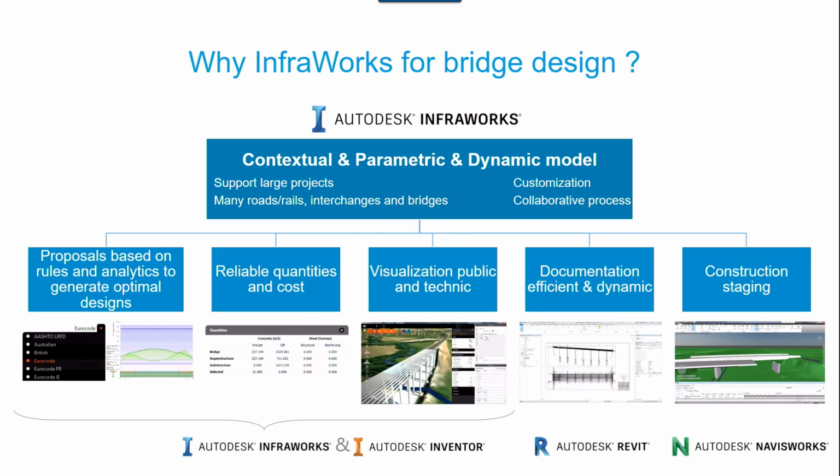You don't create the model floating in space like you can do in Revit, for example. All the 3D objects you use in InfraWorks are parametric objects. They are able to automatically adapt themselves to the situation, and you have a lot of parameters you can manage with these objects.